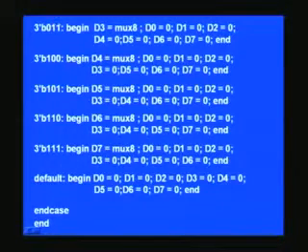And this is a continuation of the same thing, assigning different things. And finally, if you see for the 111 input, you have mux 8 assigned to D7 as such. And we have one default here. There is no guarantee these inputs are exactly valid numbers. It may be an X, that's a don't care, or even a Z, a tri-state condition. And in other cases, you may not have used all these conditions. In such a case, this default is a mandatory thing. Otherwise, it will infer a latch, and you will run into problems later on.